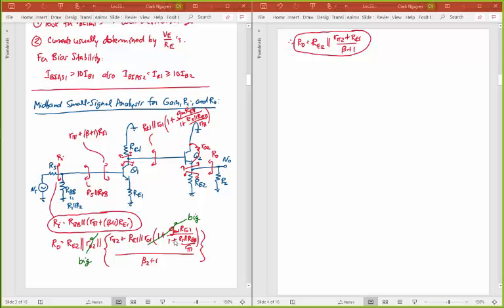On an exam, I just say resistance looking down that way is big, and I just write RC1, unless the exam says to explicitly write it down. If the exam just says get me R naught, I wouldn't even write that big thing. I would just put RC1 down. So you could do this a lot faster than I just did it by just ignoring these big things. And that's going to be the big secret to inspection analysis. What can you ignore, what can you not ignore? Okay, and so now let's keep going with this. Let's get the gain. Let me do that in green now.